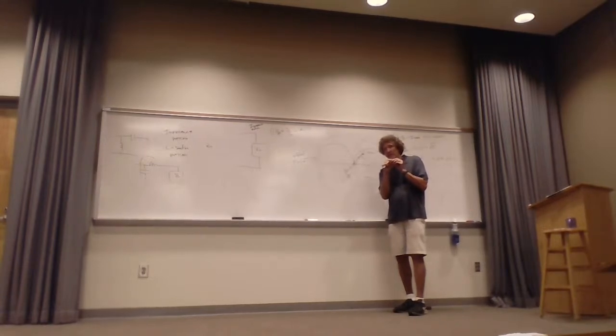With FETs, typically, it's basically a capacitor, so you don't need that. But with BJTs, you do. And so I'm just telling you this much, that if you can at all avoid it, you'd never want an inductor in parallel with the load. You always want series for an inductor because it'll allow DC current to flow, and a capacitor in parallel. Follow me, guys? All right.